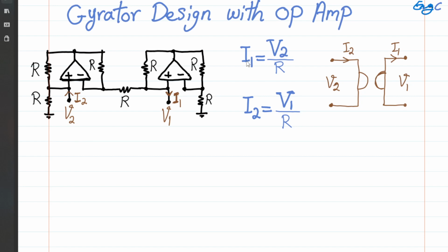Okay, let's see why in this circuit with this connection we have this interesting relationship between the current and voltages of the two ports shown here. One side note: we make the assumption that the two op-amps are properly biased. The supply voltages, not shown here, are properly connected and selected so that the op-amps are operating in the linear region of operation. We also assume that the negative feedback is more powerful than the positive, which is the case. Therefore, these op-amps are not saturated and are operating in the linear region. With that in mind, let's see what's going on here.